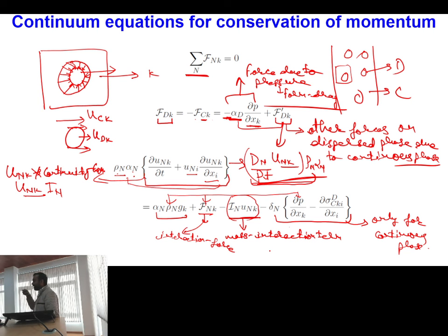So if the mass of vapor phase is growing, of course there will be growth in its momentum. On the contrary, if you take a condensation process, there vapor is being converted into liquid. So the liquid phase will have a gain of momentum because of the mass exchange, and the vapor phase will have a loss of momentum. Is this one clear? So to account for that, we have written like this. So this is now, again, a different form of the individual phase momentum equation, IPM. Okay. All are clear with this idea?